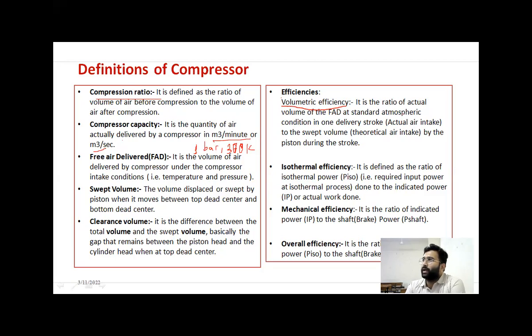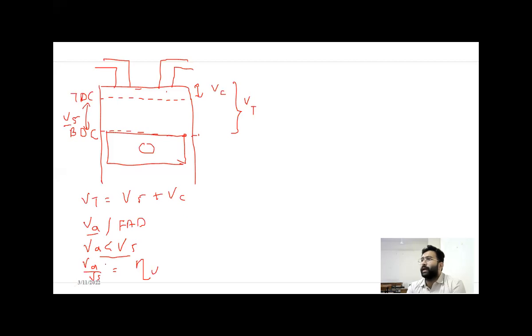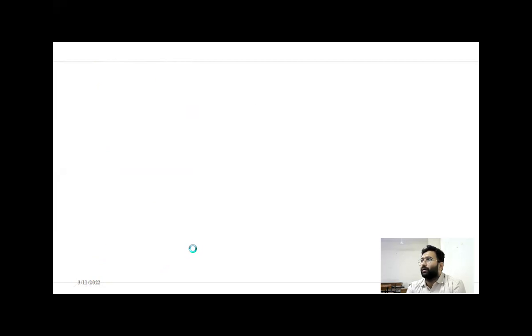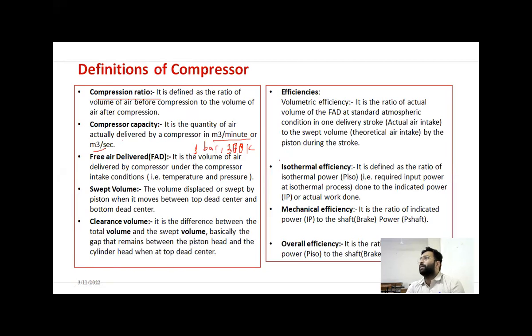At that condition, actual air delivered divided by swept volume will be the volumetric efficiency, which I just told you in this diagram. So write down volumetric efficiency.